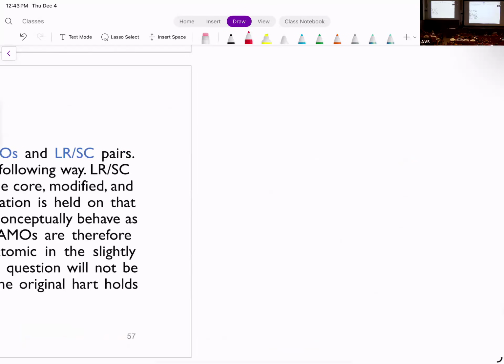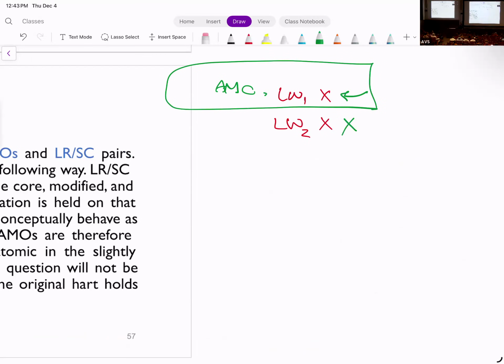For AMO, if there are two accesses to the load address X from different cores, core number 1 and core number 2, and this one is an AMO load, for example, an AMO something, what it does is that it serves this, but it blocks this. It doesn't even provide any response to it. It buffers this request.